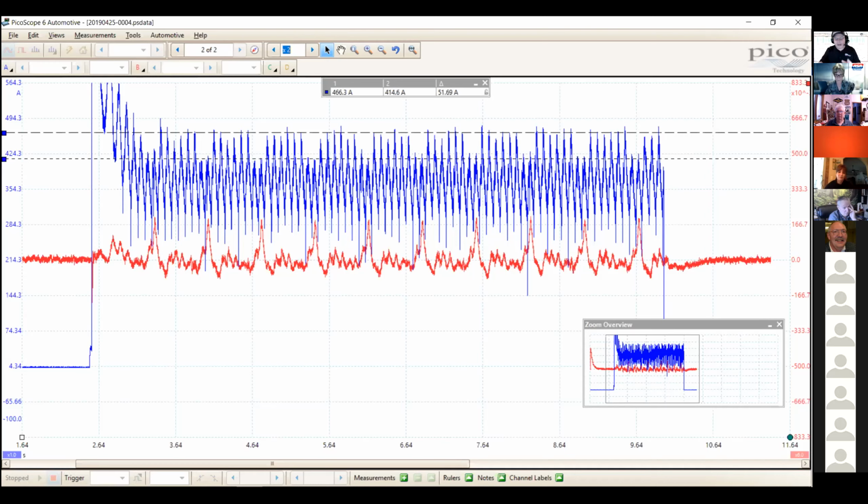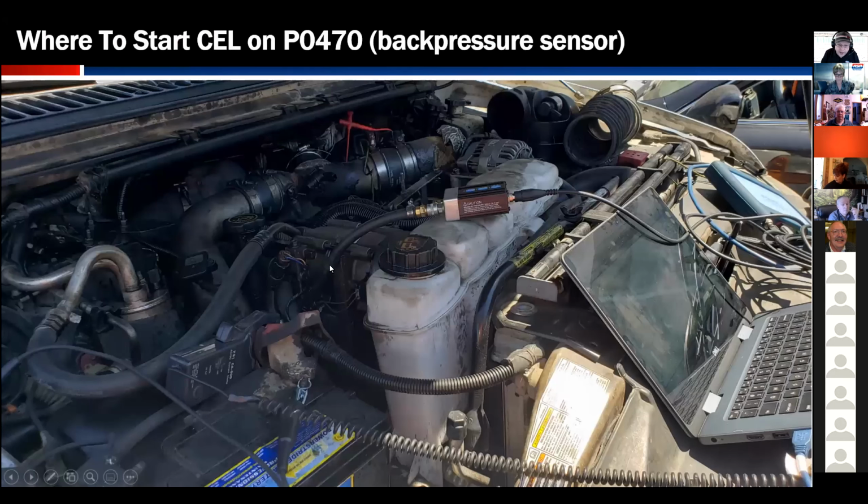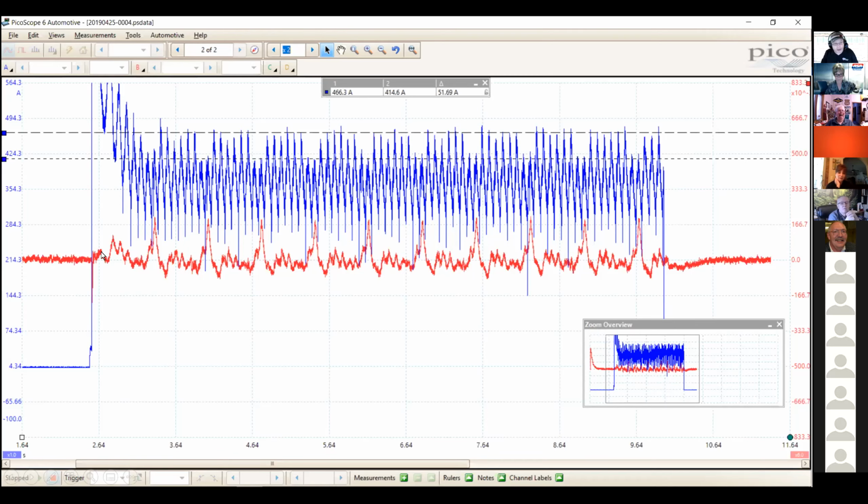But adding the dynamics of my crankcase pressure, which you see in red, or this channel B, you will notice that at the same point in time, and this is why these 2 tests go so good together, at the same point I have low compression, I have bursts of pressure in the crankcase. Guys, once again, man, it's game over. Ain't no cylinder heads in the world gonna fix this, man. This thing has problems with blow by from the pistons.